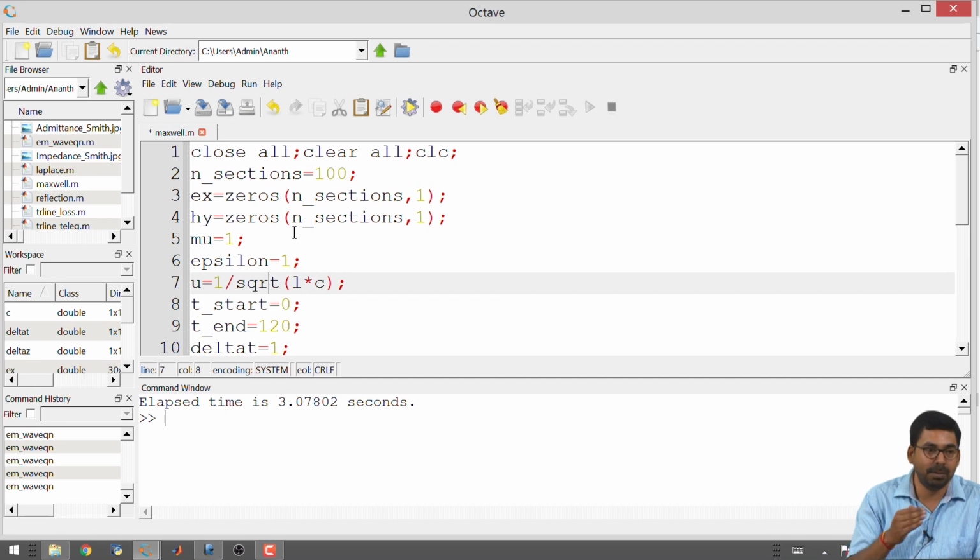And then when you have finished with the simulation, you try to figure out that one velocity corresponds to say 3 times 10 to the power 8 meter per second, and I will scale it accordingly. So, this kind of simulation is very popular. It is also being used in other open source software like MEEP, MIT electromagnetic propagation software. They use normalized units where the velocity is made equal to 1 for vacuum.